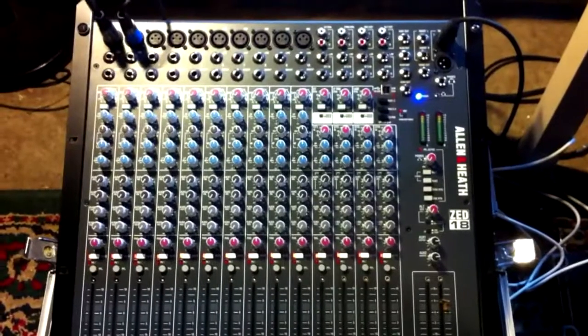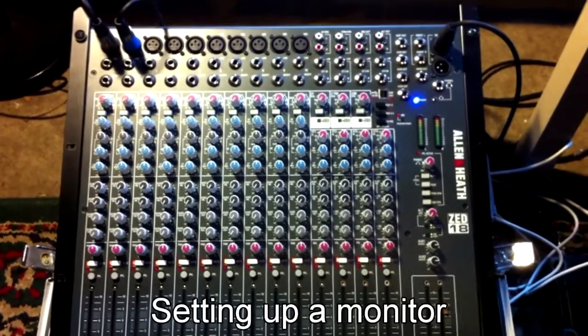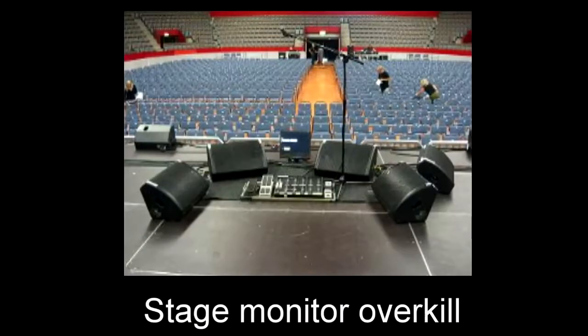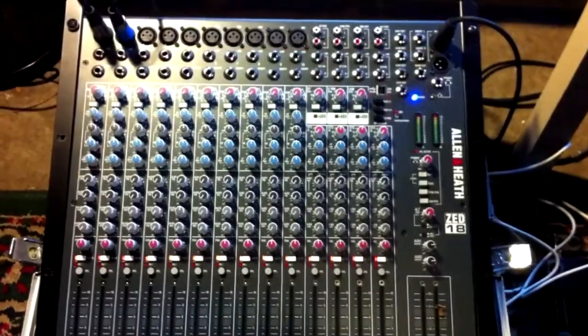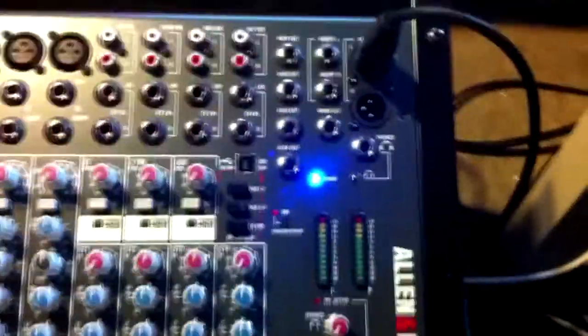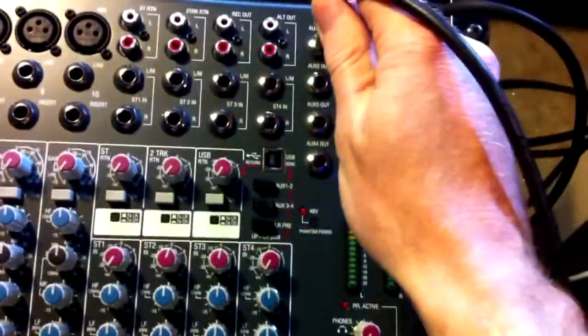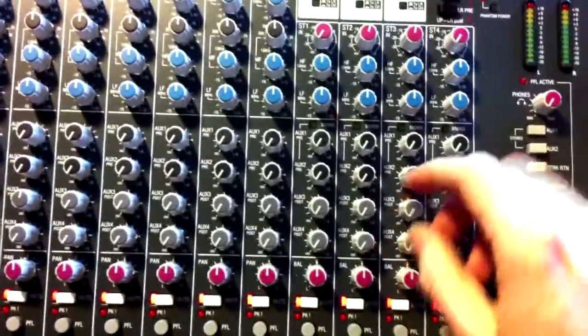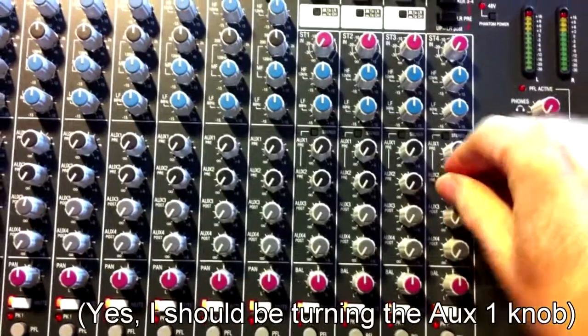Something that you will use the auxiliary channels for is setting up a monitor. You will set up a monitor so that your musicians or speakers can hear themselves, and lots of times that mix will be different than your main mix coming out of the big speakers. So for this, you will just plug whatever monitor speaker you have facing your musicians into the auxiliary output channel. And then you will just have to keep in mind all your auxiliary channel controls.